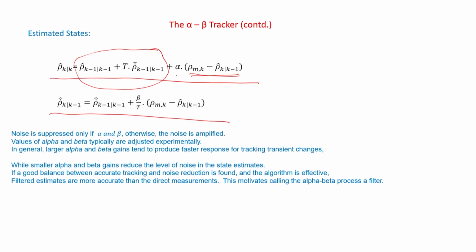Okay. Similarly, beta is your predicted beta by t into the innovation, measured minus predicted measurement. So, you can clearly see there is only a state update, there is no covariance update, and no online gain update, because alpha and beta are constant in the alpha beta filter. In those days there were no computers and no Kalman filter, but this thing actually works.